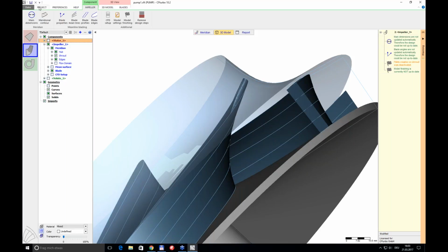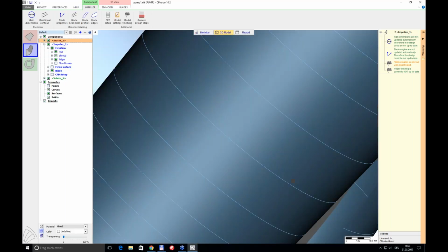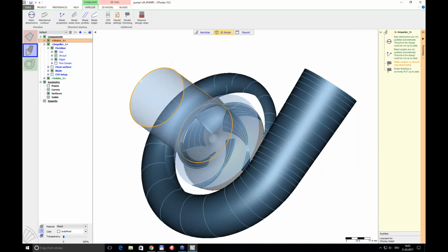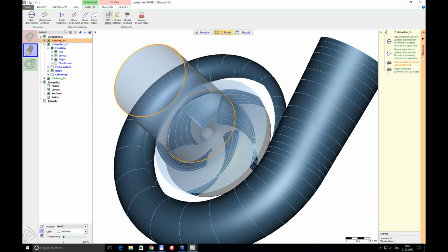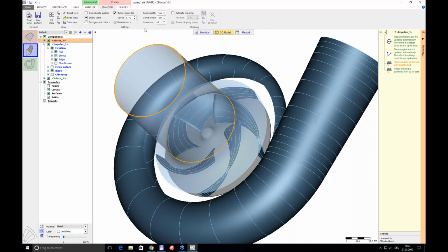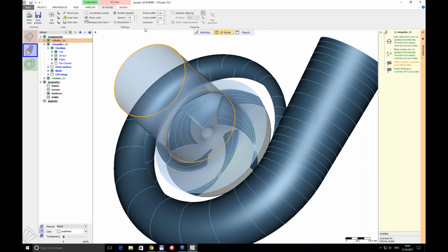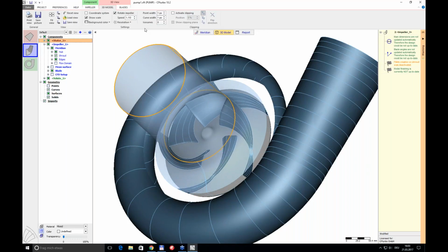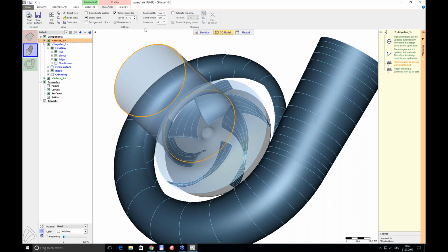Which turbulence models are available? The question from Taha. Again, quickly, currently in the user interface, there's K omega SST, K epsilon, and laminar for various tests, and those are just in the graphical interface. Of course, TurboMachinery CFD is fully compatible with standard OpenFOAM. It's 100% compatible with standard OpenFOAM, so you can put your own turbulence models very easily. You can write the case down on the disk, and then change the turbulence properties and run the simulation this way, or you can use a Python script, very easy, very simple.